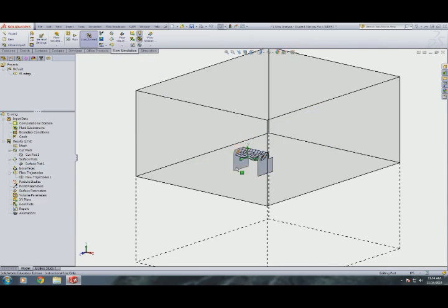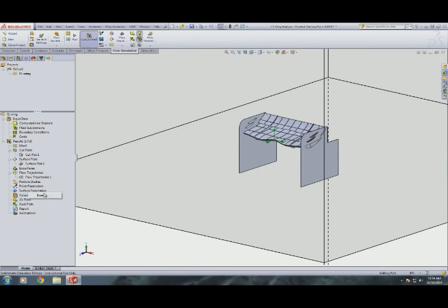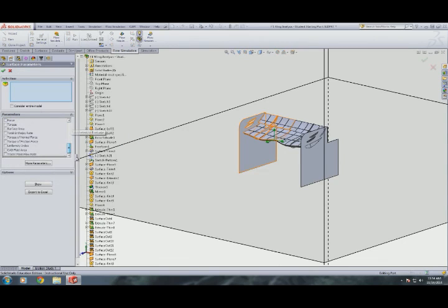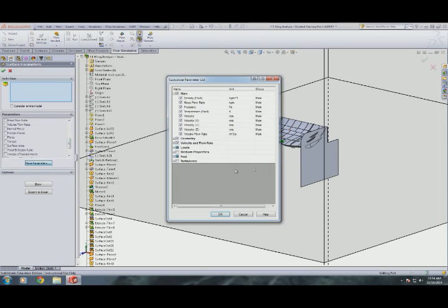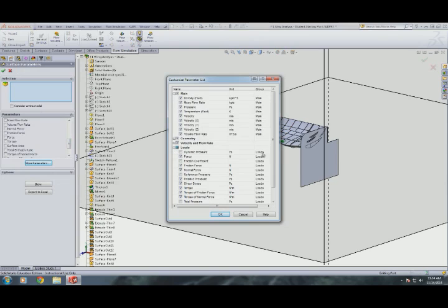So to do that, you do surface parameters, insert. We need to go down and look for force, which in my situation is already here, but if it's not already loaded on yours, it'll be underneath loads. Force is right there. Look at all this stuff you can calculate and integrate for parts. It's pretty cool. So you check force, it'll be newtons.